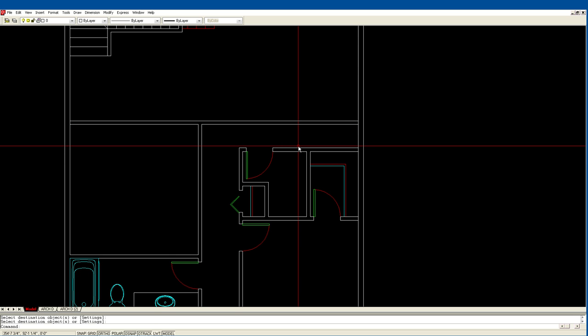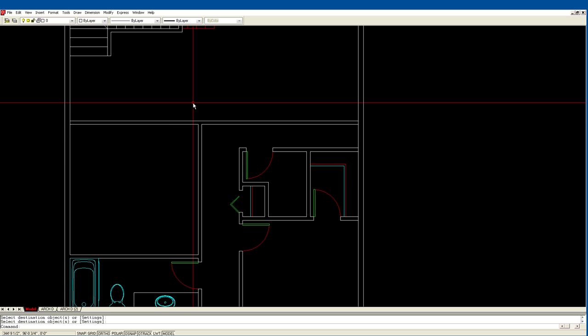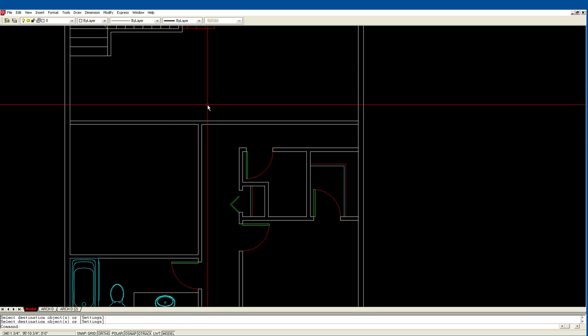Now, this will be our kitchen on the other side of here. We'll start our kitchen, and we 45 the wall here. Well, that 45, they want double doors, and so if I give them 2 30-inch doors, that would be 60 inches. Plus, like I said, I need another 2 inches for rough opening. So I need a 62-inch opening with 4 inches on the other side. So 62 and 8 is, what is that?